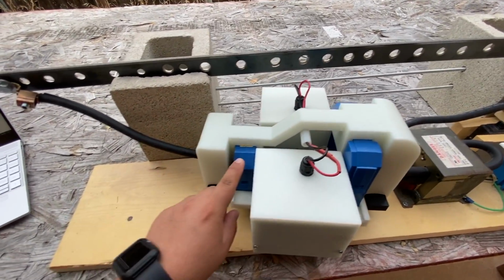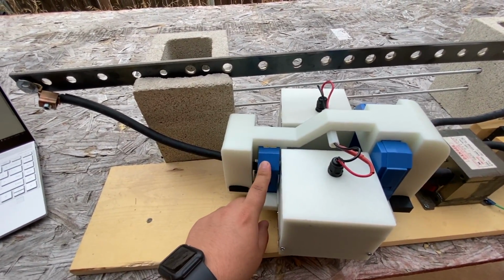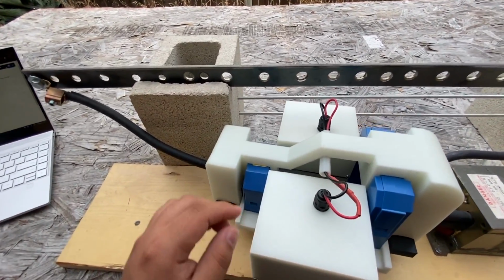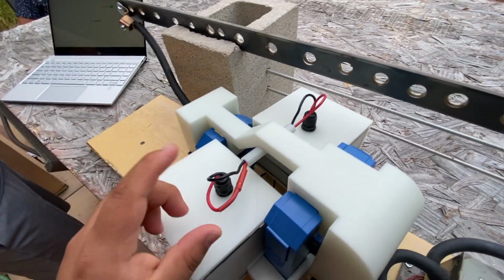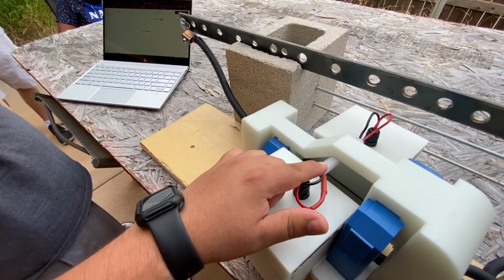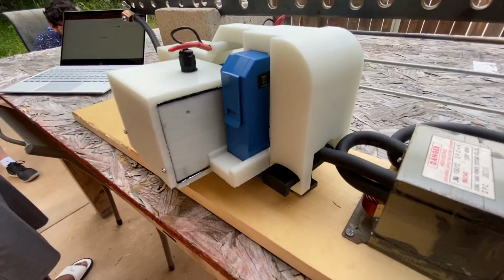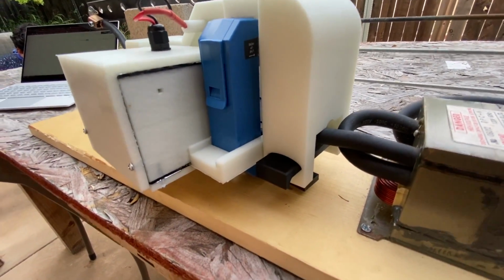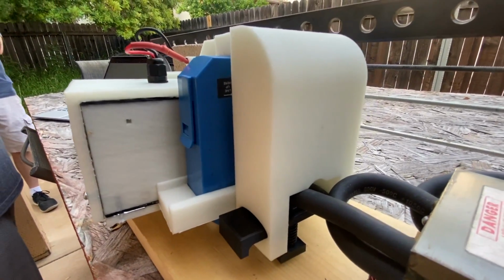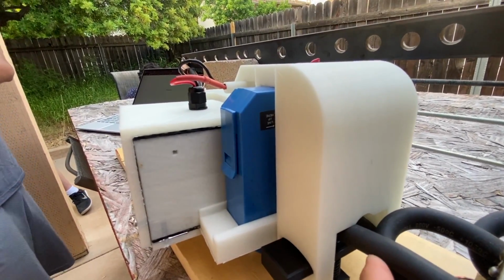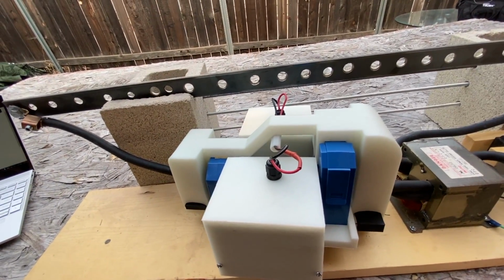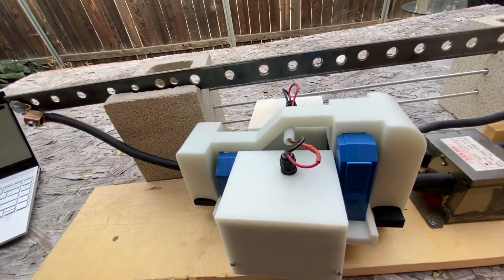So just a quick overview on the overall chassis design. This top clip pretty much holds the current sensing current transformer and the power-based current transformer. The 5-volt rail that the sensor electronics needs on this side clip is powered from the power electronics side, and the 5-volt rail is channeled through this upper channel seen on the top clip. In order to mount onto a distribution line, there's a clamping mechanism where this screw essentially is threaded upwards, and it applies pressure to this little cutout. The overall chassis is made so that it's easy to install and take off a distribution line.